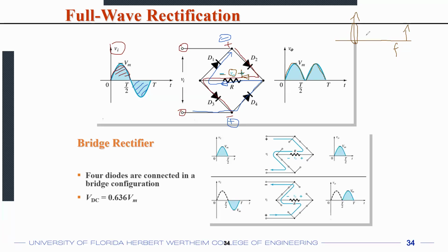So a very high frequency signal, if it does not have any DC component and you do low-pass filtering, you'll just get 0, right? A sine wave, it does not matter whether it's a low frequency or a high frequency. The average value of a sine wave is 0. So there's no DC component, whether it's a low frequency sine wave or a high frequency sine wave. Only if you have a DC component, or only if you, let's say, create a half-wave rectified signal or a full-wave rectified signal, then you start seeing a DC. That is the average value of the rectified signal, right?